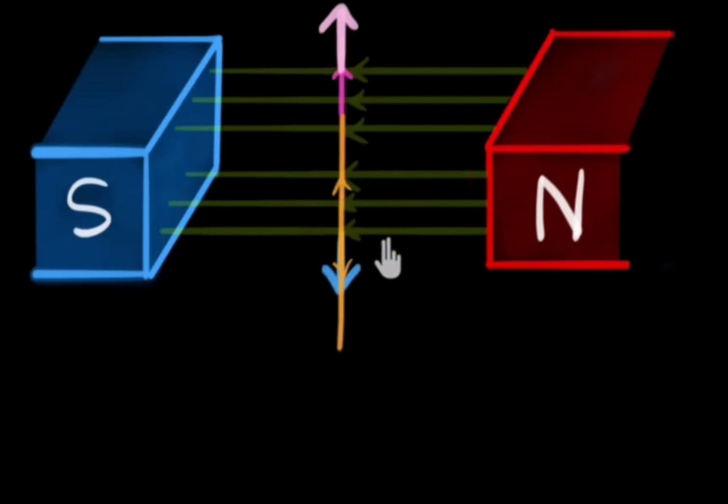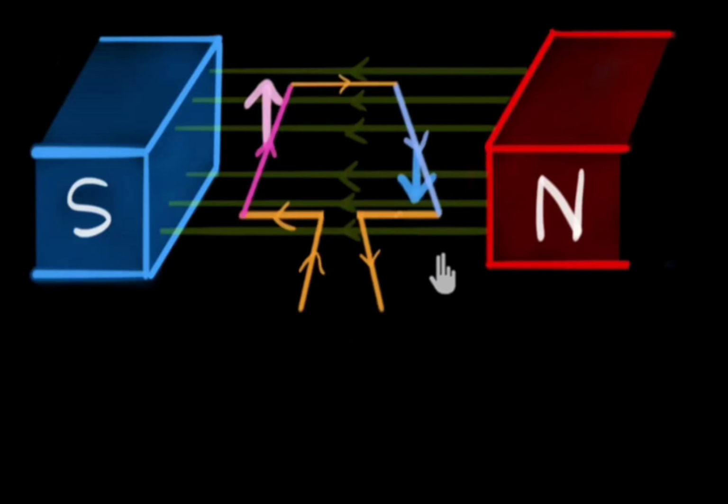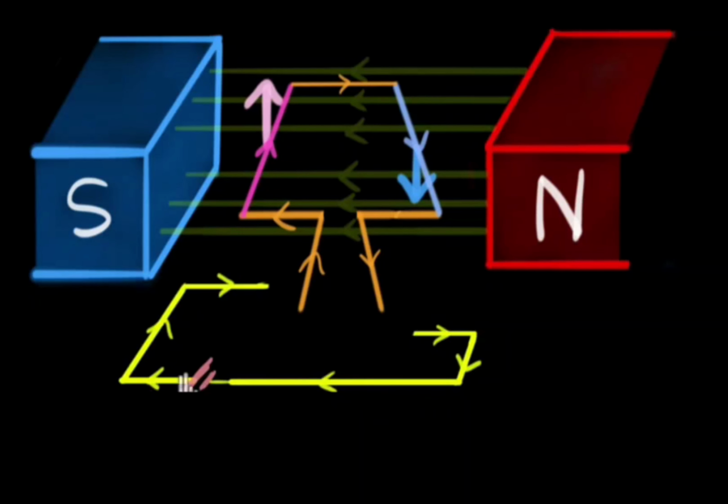In the DC motor, when the armature rotates, the conductors on it cut the lines of force of the magnetic field in which they revolve, so that an EMF is induced in the armature as in the generator. The induced EMF acts in opposition to the current in the machine and therefore to the applied voltage, so it is customarily referred to as back EMF.